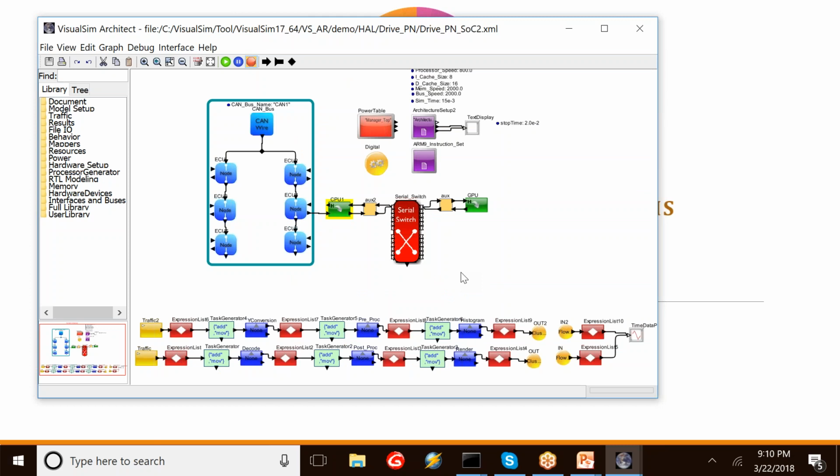So it gives you full visibility into what exactly your system is doing in terms of both getting inside visibility, like what's happening in the pipeline, what's the cache hit miss ratio, how much of memory is consumed, but also getting visibility into how much of power is consumed for each of the tasks. Gives you both of those types of visibility as well.